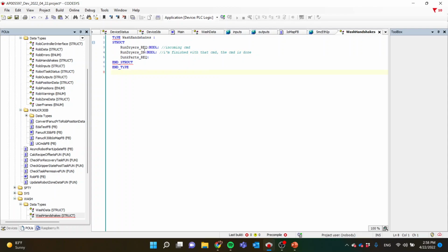Okay, so I'm either going to give you this bit or I'm going to fault out. So if you give me a run dryers request, I'm going to do what you told me to do, and you're going to sit there and hold that request, and wait until you see the run dryers done bit, and then you're going to drop your request, or you're going to see me fault out, trigger an error, and then you're going to react yourself in your logic. Only two outcomes possible.